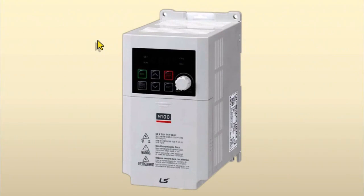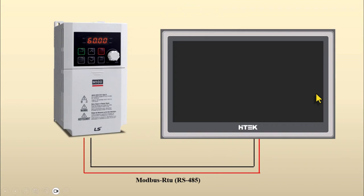In continuation of our series of instructional videos about the LS brand M100 inverter, today we want to discuss another very useful feature of the M100 inverter. In these instructional videos, we are going to demonstrate step by step exactly how to connect the M100 inverter to another device using the MODBUS-RTU protocol. We will learn about the RS-485 network and see exactly what settings need to be configured on the inverter. And also, how exactly should the wiring for the inverter be done in the RS-485 network.